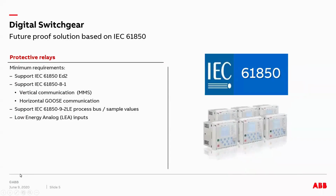Okay, so what is the minimum requirement for a digital switchgear? Obviously, as we discussed, the protective relays, the IEDs, should support the IEC 61850 standard completely. It should support 61850 Edition 2. It should support IEC 61850 8-1, which is the station bus standard, which involves vertical communication, MMS, which we mentioned, and also GOOSE communication, which is a horizontal communication. And it should also support 61850-9-2 LE process bus, or the sample values, as we mentioned.